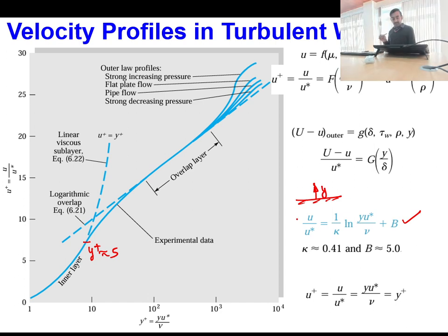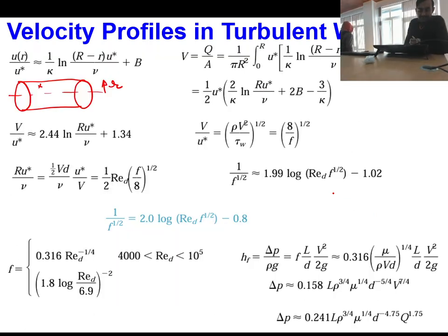So whenever I write the commensurate form of this velocity profile for the case of pipe flow, I have to consider the equivalent distance to that of y. That distance I have to measure from the solid boundary of the pipe. In this pipe flow, my outer radius of the pipe is capital R, and the point I am referring to is small r. So with reference to the wall, the distance of the point at which I am interested in finding the velocity is capital R minus small r.